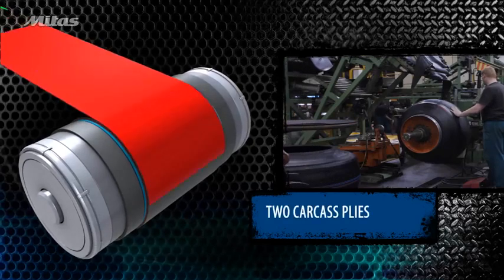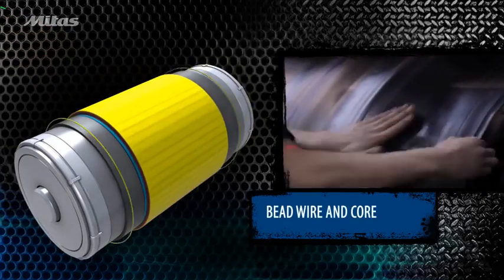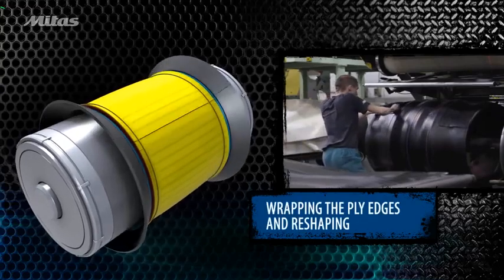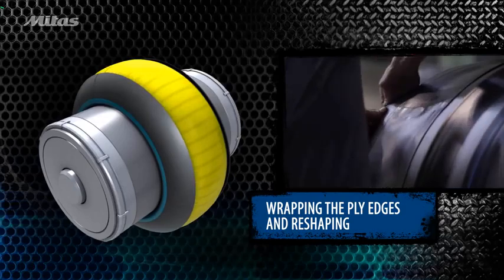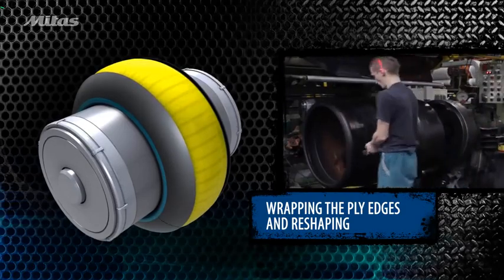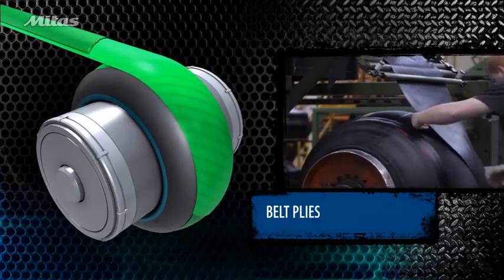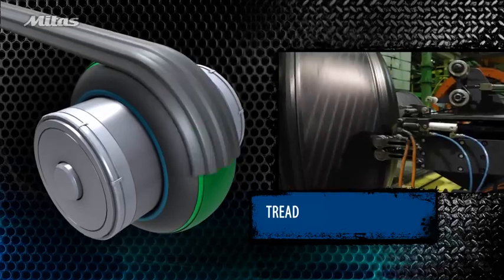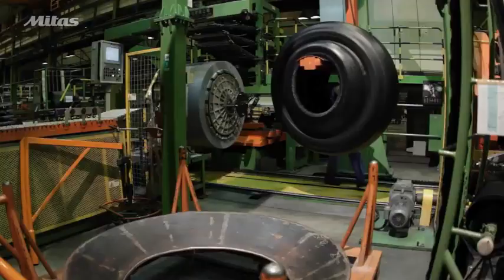And two carcass plies. Bead cores are placed on the building drum. Then the ply edges are wrapped around the bead core and the sidewalls are moved into position while the tire is reshaped. After inflation, the belts and tread rubber are applied. For large tires, the tread rubber is wound onto belt plies. This process achieves a green tire that already resembles the final product.